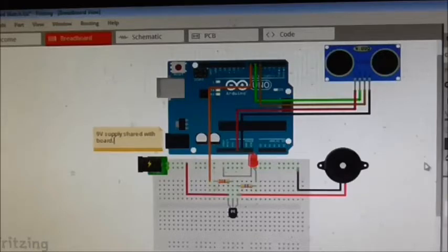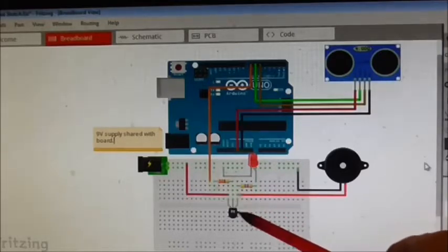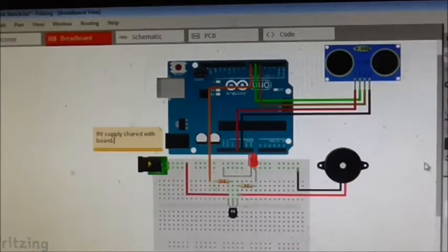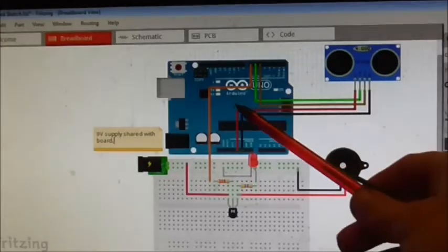This is the point where the project's getting truly digital now. It's been digital so far only in the sense that it's been binary. Either there's a pulse at the base or there isn't. And what I've got in front of me here is a wiring diagram of what I intend to do next. And as you can see, this is the circuit we've already seen, the NPN transistor and the mechanical buzzer and the LED from the last section of the video. We've got rid of the capacitor and we've got rid of the thyristor because what's going to do that job is this thing up here.